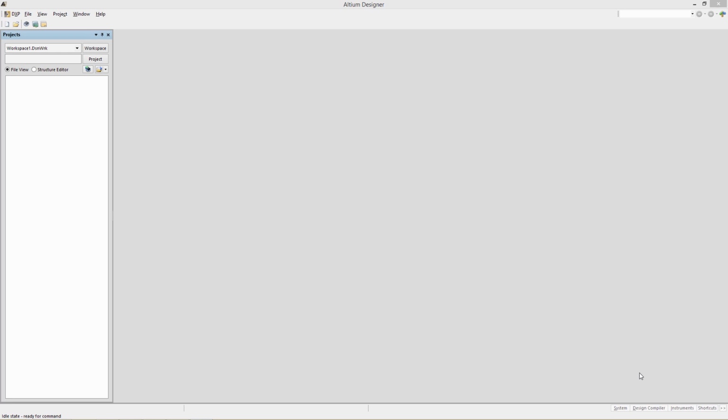Configuring simulation parameters. Simulation parameters can be adjusted to change the electrical characteristics of the device being simulated without requiring modification of the underlying simulation model. For example, the value of a resistor, capacitor, voltage source, or initial condition.